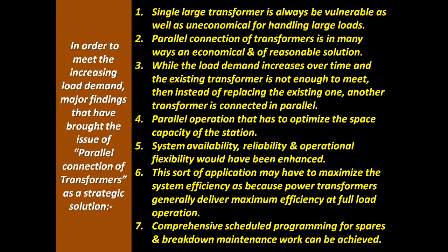Number 2, parallel connection of transformers is in many ways economical and a reasonable solution. Number 3, while the load demand increases over time and the existing transformer is not enough to meet that demand, then instead of replacing the existing one, another transformer is connected in parallel.